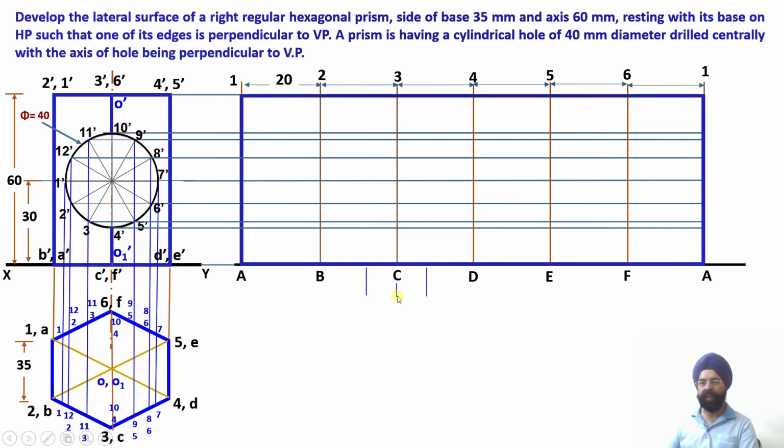This is my center 3C. I have measured these two distances, C3 and C5. So these distances have been measured. If I say this is 3, then 11 will also lie here. If I say this is 5, then point 9 will also lie on the same vertical edge. Just see, two vertical projectors have been created over here, right? Next, from 3C, the distances of 12, 2 and 8, 6 will again be equal, so now I can do the second marking.